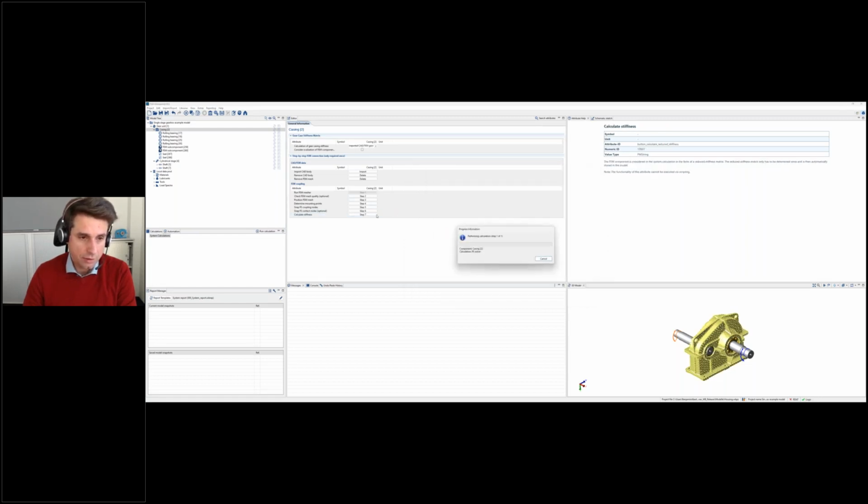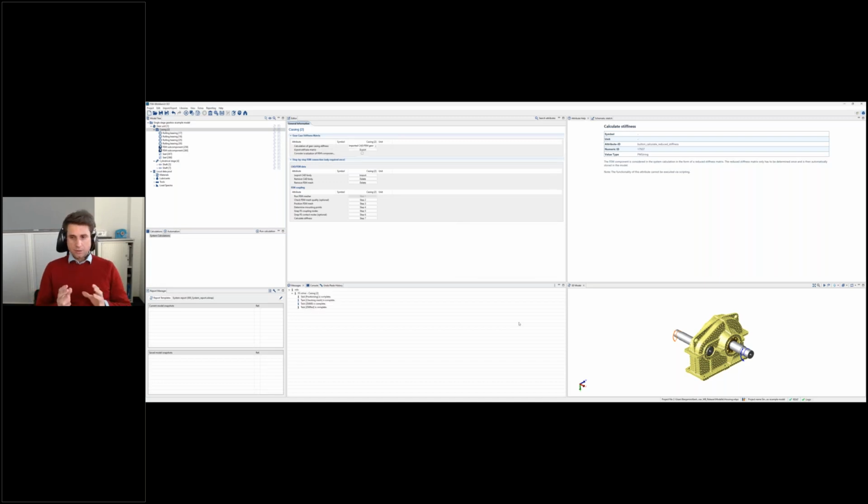And then we can click calculate stiffness as a 7th step, and this concludes the multi-part housing. Again, this allows you to import quite complex housings and mesh them in accordance to each part of the housing. So each part of the housing can have a little bit different meshing characteristics, and it's not required that you mesh it in total and as a whole geometry at once.